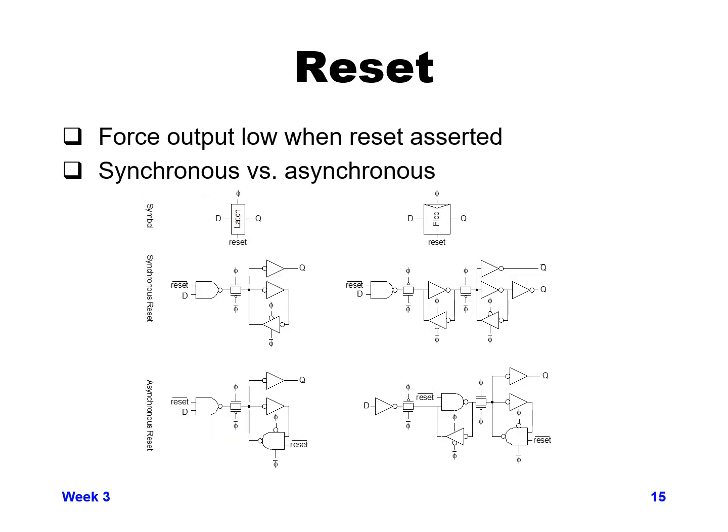Another feature that is added commonly to both latches and flops is a reset function. So a lot of times you want to say, okay, we're either capturing data, or there could be a global reset that comes through the system and says, I just want to reset everything and start from scratch. Implementing a reset function, there's a couple different ways we can do it. Down below we have shown a latch and a flop, and how you might implement reset in a latch versus a flop, and the two different types of reset.